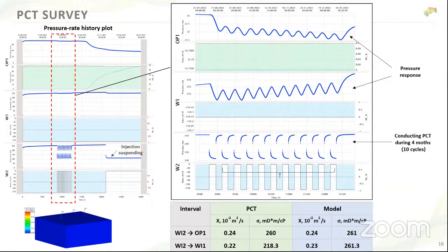But anyway, it's maybe 2000 times less than the production deferment for the standard pressure interference test, when we shut the observation wells, wait until the pressure stabilized, then create the pulses, look at those pulses in the observation wells, and then start them again. That would be a huge production deferment.